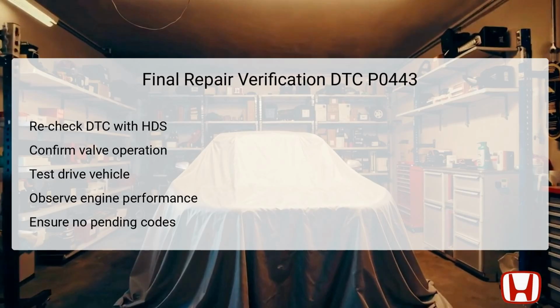During this drive, carefully observe the engine's performance under various conditions, including acceleration and idling scenarios, to ensure smooth operation and no lingering symptoms. It's vital to check that there are no pending codes or check engine lights illuminated after the drive, as this verifies that the repairs were successful. If all systems appear to function correctly, you can safely conclude the repair process for DTC P0443.